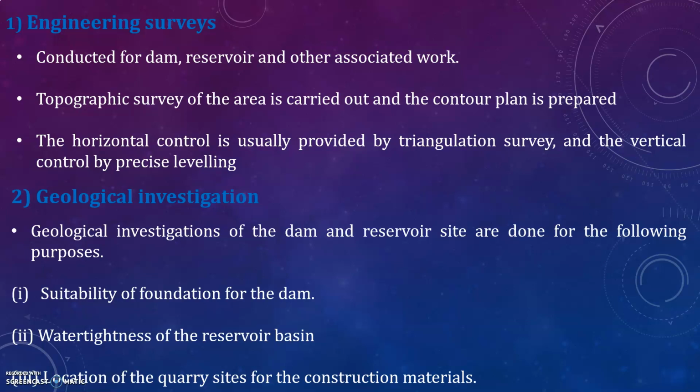Geological investigations are required to give detailed information about the following items. As I already told, that is water tightness of the reservoir basin and suitability of the foundation for the dam, then geological and structural features such as folds, faults, fissures, etc. of the rocks in the basin, then type and depth of the overburden, and location of permeable and soluble rocks, if any, groundwater conditions in the region, and location of quarry sites for the construction materials.